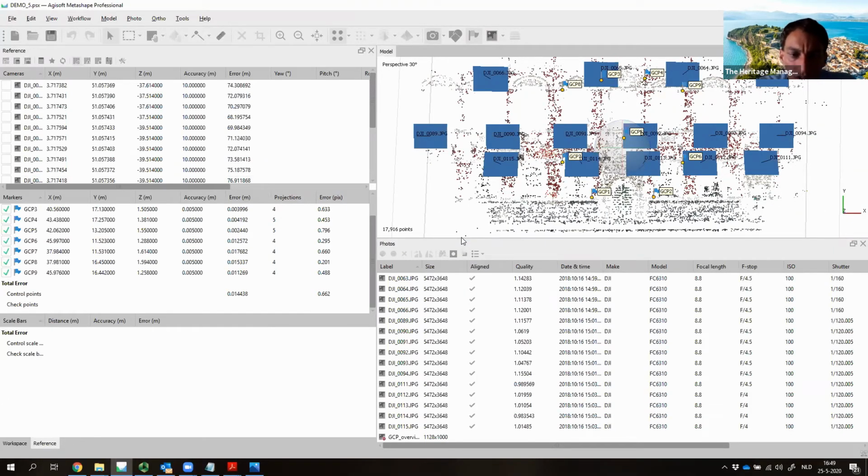After saving my project, I can actually use these ground control points to optimize the quality of my image alignment. So the image alignment itself and also the correction, the self-calibration of my entire model, was solely based on the images. What I'm actually doing now is adding a new constraint to my model, saying that, okay, these pixels should be related to each other, but they are not only related because of the pixels, but also because of the ground control points that I assign to them.